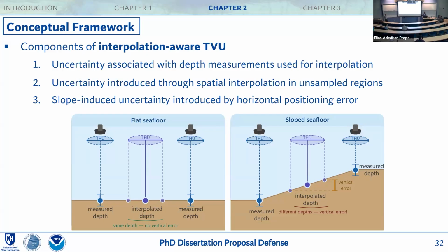Yeah, for example, an ideal test bed would be something that has a relatively flat seafloor and also something more rugged, so that I can really demonstrate what I was saying: you have wider line spacings where the seafloor is relatively flat, and as you go into more of a rugged or complex seafloor, you bring your line spacings together, if that answers your question.